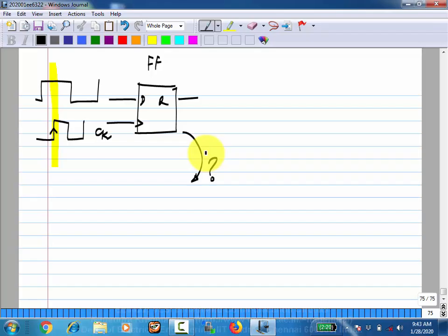Yeah, so let's not go down to that kind of low level description. Let's say we typically model all our circuits with control sources, right? Imagine that the MOS transistor is a voltage controlled current source. So you had voltage controlled current sources and some other components. How would you make something that takes a small signal and determines the sign? What could you do? What do you have to do?